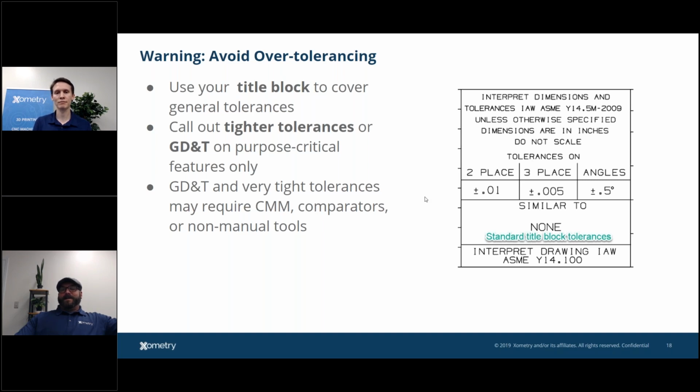The other thing I would say is don't use hybrid prints. I've seen several customers that call out plus or minus 5 in their tolerance block in inches, and then the rest of the print's done in metric. Or they have some metric tolerances here and some English tolerances here, and then it gets very confusing for QC. It gets very confusing for the machinists. Just keep it simple.